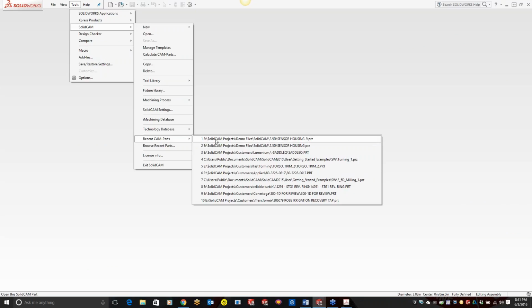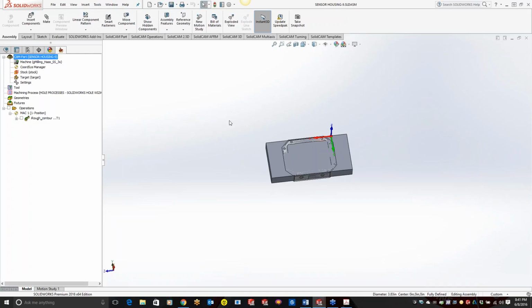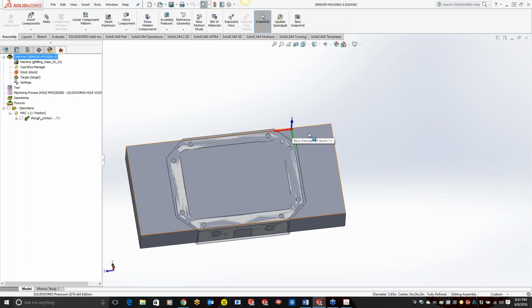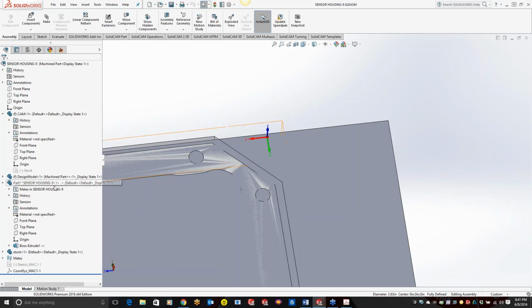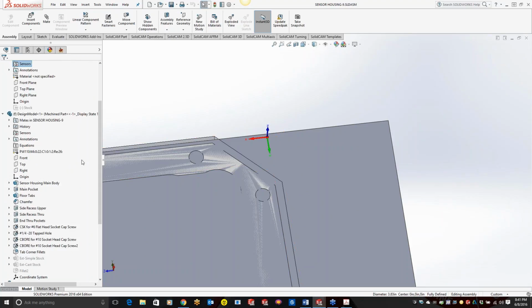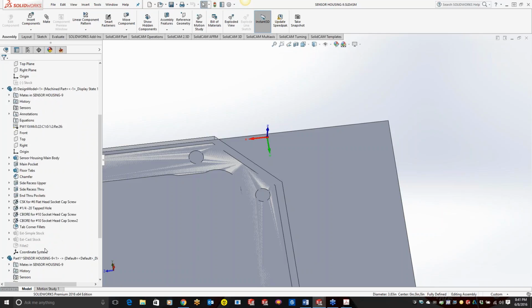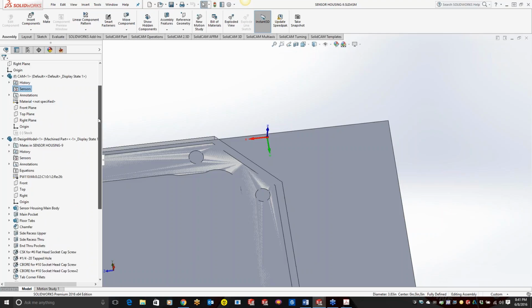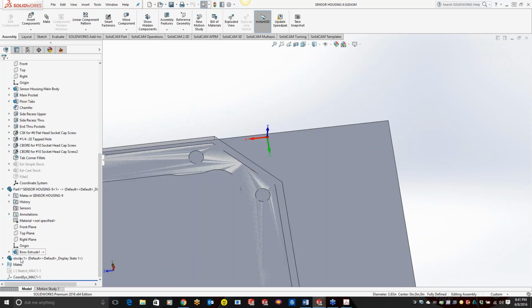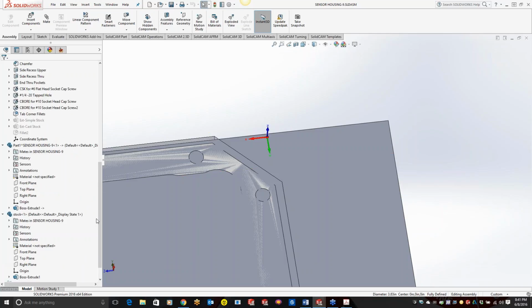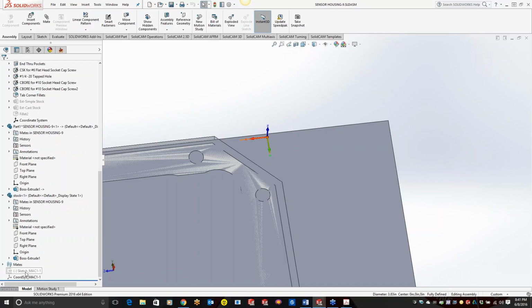What he's asking is, with the coordinate system, there is no way to measure where that is. There is nothing there for you. What you can do is inside SolidWorks, expand out the design model, and there should be a 3D sketch representation of your coordinate system.